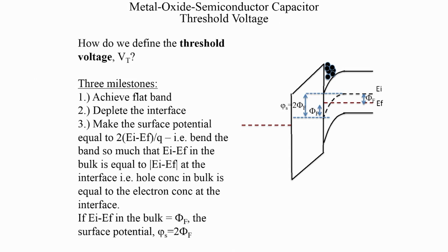Let us now start coming to a more quantitative definition of threshold voltage, because it is such a useful modeling parameter. But you must remember, as I mentioned, in semiconductors the electrons are not waiting for the gate voltage to cross the threshold voltage before they invert. There is some weak inversion happening even before the surface potential reaches 2 phi f. The moment the surface potential increases beyond phi f, you have electrons appearing quite rapidly at the interface, and these are all thermally generated electrons.